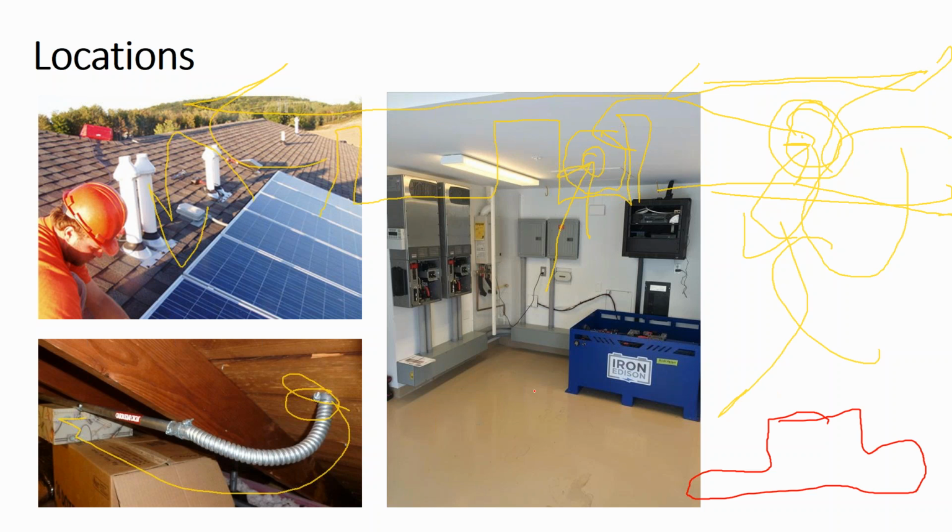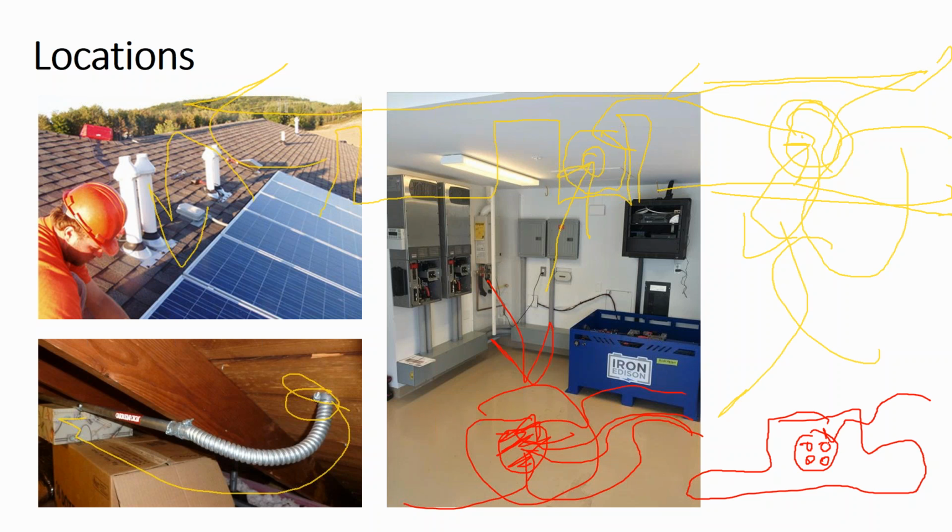But back on this hole, you can find a fitting that is just a 3/4 inch hole for putting a 3/4 inch conduit or cable into it. Or you might be able to squeeze 4 solar cables into it. But there's actually a fitting you can find that comes with a seal and 4 little holes in it that are sized for each number 10 conductor to go into. It costs a little bit more money, and sometimes you can't find it off the shelf at Home Depot, but you have to order it online.